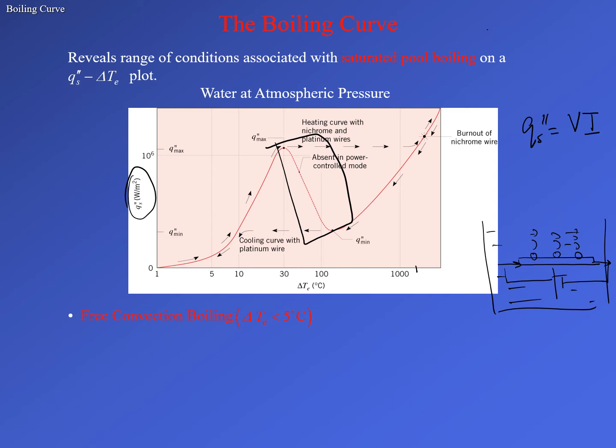As you know, the boiling point can be controlled by changing the atmospheric pressure. So the temperature could be controlled for the wire, and that resulted in this dashed part of the curve being obtained. As the surface temperature of the platinum wire was controlled continuously, we saw that while increasing the surface temperature, this curve was obtained, and while decreasing, we could retrace this curve back. Okay.